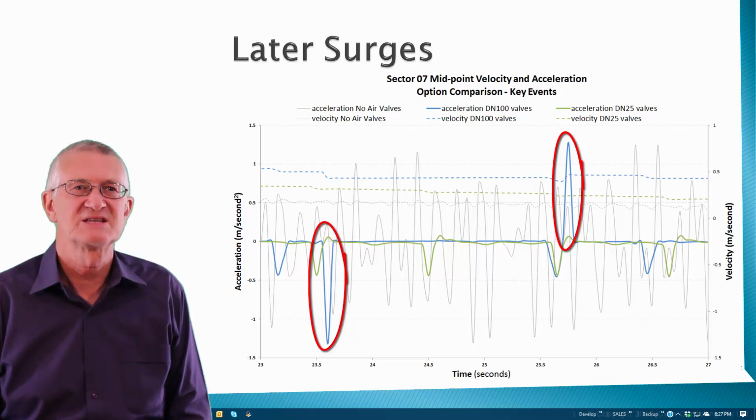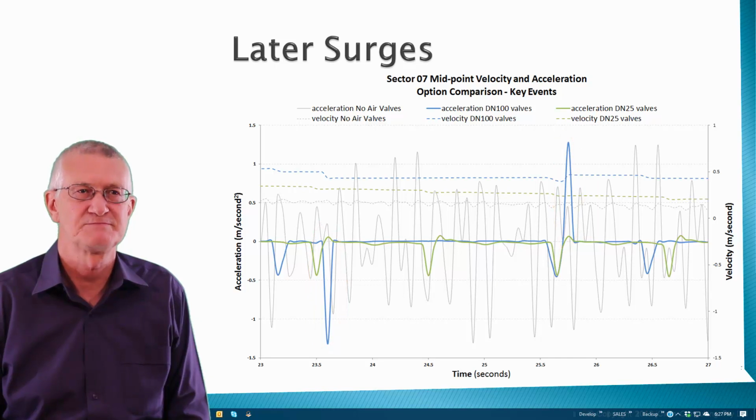Yet when these accelerations occur, the hydraulic grade line is not well above the ground profile, it is down near the pipe obvert. End result, negative minimum heads, and at times low enough to reach vapor head.